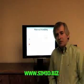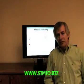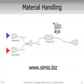Okay, our simple source server sink model shows how easy it is to build a very simple model. Now we're going to turn our attention to a little more complex model. In this case, our system consists of two different types of entities, and they come into the system at different rates. Then they move on to accumulating conveyors, and each accumulating conveyor moves at a different rate and merges together onto a slower conveyor. So we have two different conveyors basically trying to shove entities onto a slower moving conveyor.